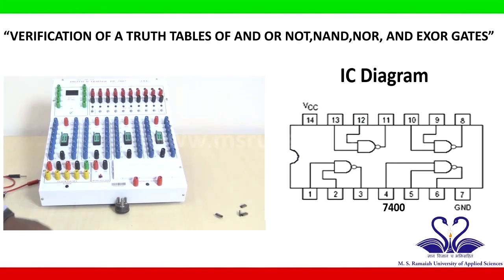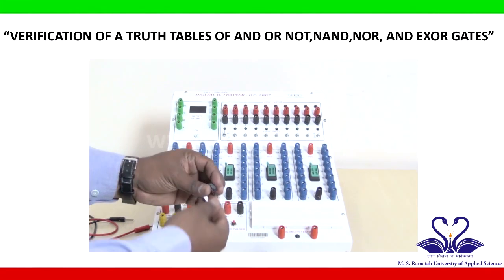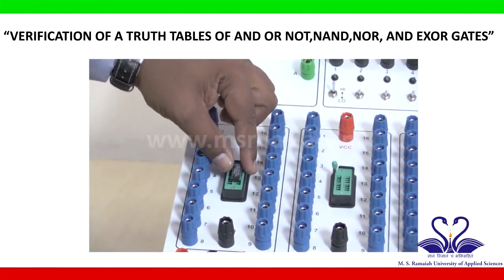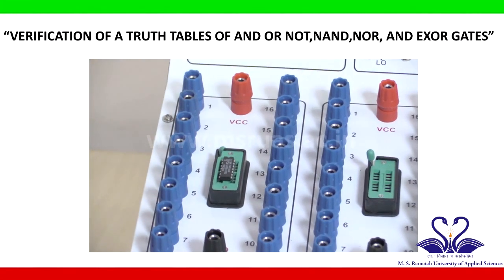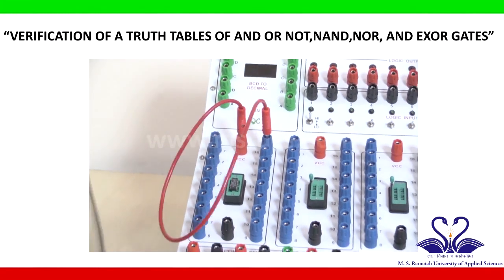Now I will verify the truth table of NAND gate based on the NAND gate IC diagram. So 7400 is a NAND gate IC. I will take a 7400 and mount it on the digital IC trainer kit such that pin number 1 should go to the first slot, and I will lock it. Based on the IC diagram, pin number 14 is connected to VCC. Pin number 7 is connected to ground.